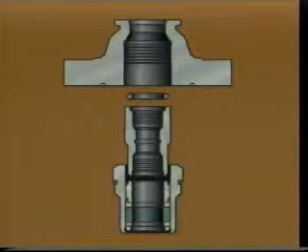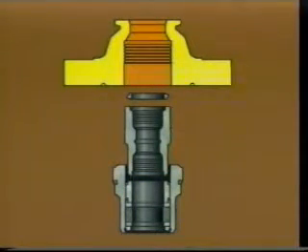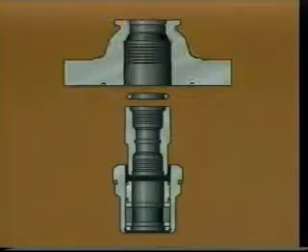A slick joint assembly, sometimes called a hook wall, is often used in lower pressure applications. Here, the tubing hanger acts only as a seal for the tubing casing annulus, and the tubing head adapter supports the weight of the tubing. The design of this hanger allows manipulation of the tubing string to set or release packers and tubing anchors.